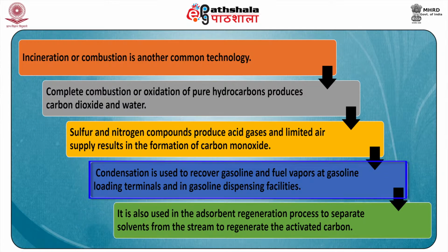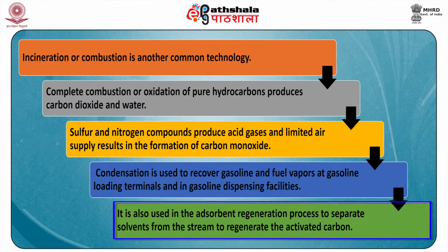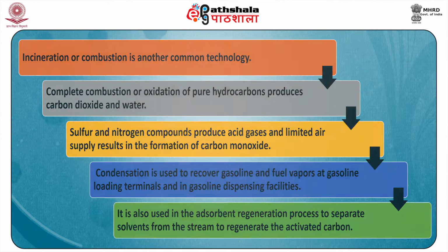Condensation is used to recover gasoline and fuel vapors at gasoline loading terminals and in gasoline dispensing facilities. It is also used in the adsorbent regeneration process to separate solvents from the stream to regenerate the activated carbon.